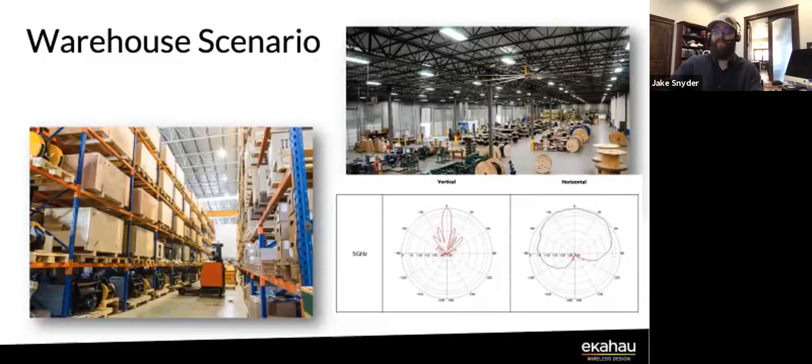So if somebody stacks a bunch of metal empty containers all the way to the ceiling, and this actually happened to me, and the directional antenna was on one side and they were trying to pick product on the other side, it didn't work. And so I like the overhead directionals pointing down. In fact, there's a number of manufacturers now that make a very narrow aisle width antenna that goes very wide in the other direction. And it keeps it so you're never trying to shoot through stuff or shoot the wrong way.